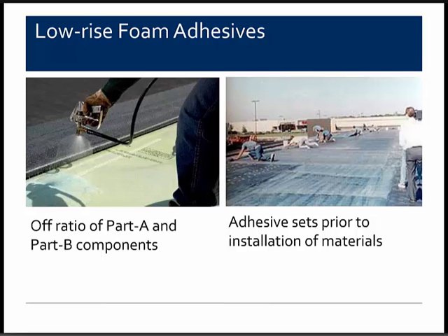The picture on the right shows the adhesive installation in a fairly large area where the contractor may have gotten ahead of himself. This type of over-installation may allow the adhesive to cure prior to bonding the two materials together.